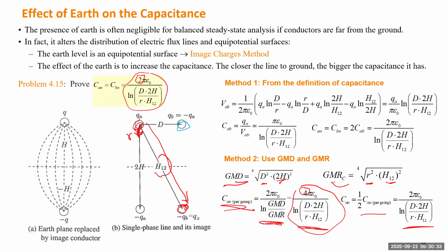So I mentioned one project I did like 15 or 16 years ago for Long Island. Long Island, they have a local power company called Long Island Power Authority. So we did the system restoration study. We helped them to evaluate their black start plan. Black start means if the system is in a complete power outage or blackout, they need to have some units they can start first. Usually such units will be gas turbines or combined cycle combustion turbines, which can start in like 10 minutes or 20 minutes.